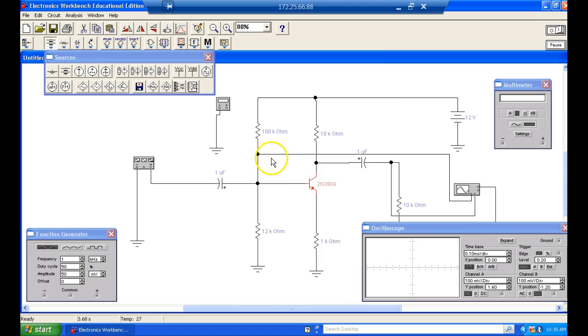So the simulation is wrong. Y'all see what I'm talking about? Because if this was a true short between here, that means whatever voltage I measured there would be exactly the same thing right there. When I come up here and look at this, this simulation is off.